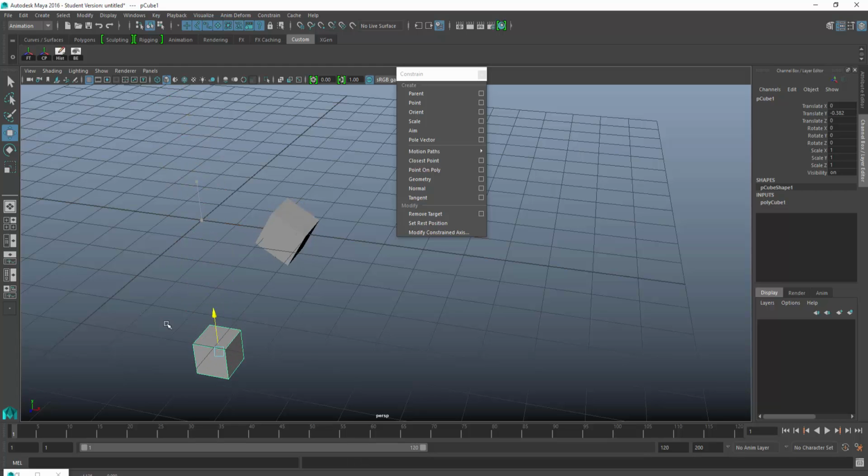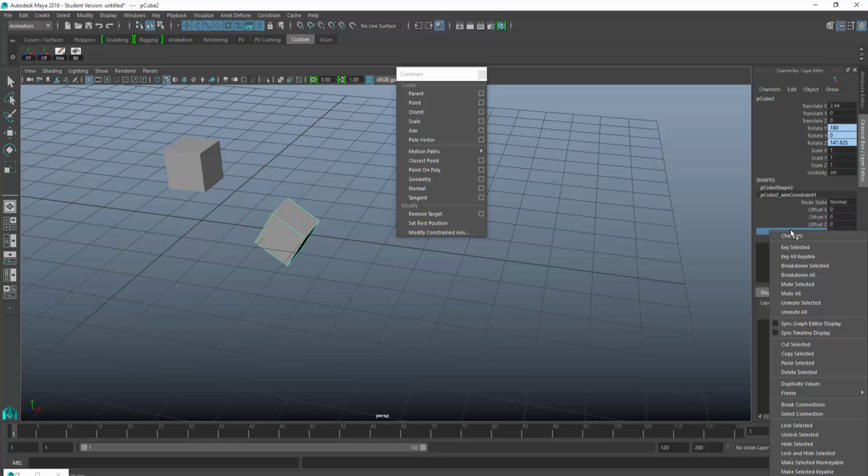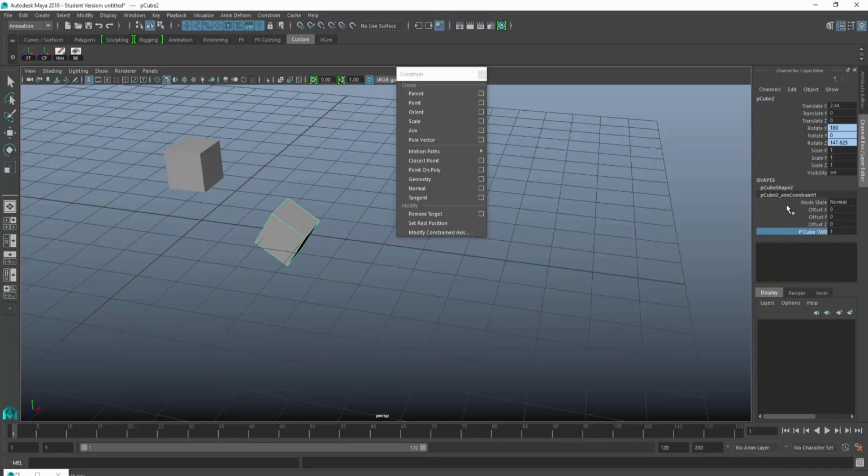So you can see here in this aim constraint how that is pulling or moving along. So that can be animated. And you can again turn that on and off by selecting this cube and clicking 0 to have it no longer follow, or 1 to have it follow. And then you would right click, set key in order to set that keyframe.